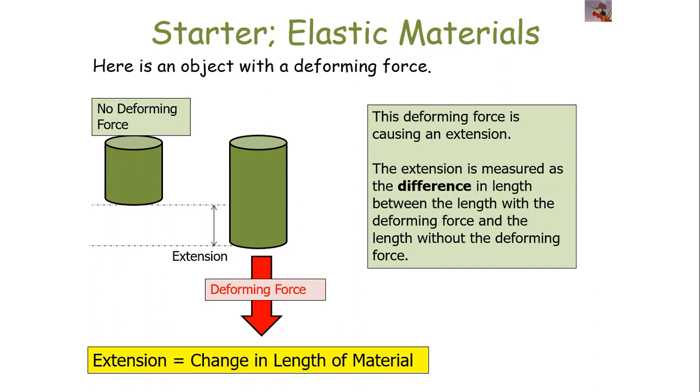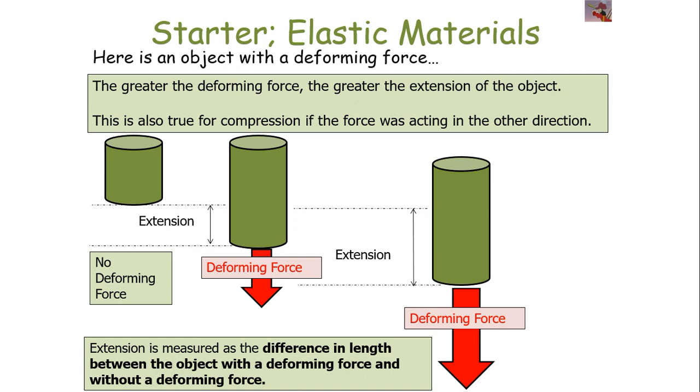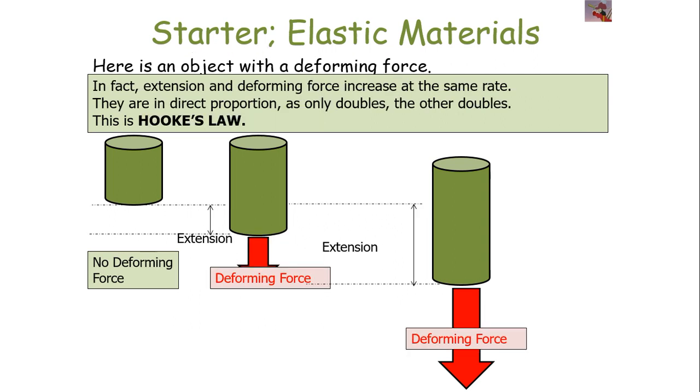So extension is the change in length of material, or delta L. So it's the length with the deforming force minus the length with no deforming force. Now, the greater the deforming force, the greater the extension of the object, but it's also true for compression as well. In fact, it was found that extension and deforming force increase at the same rate for many materials,